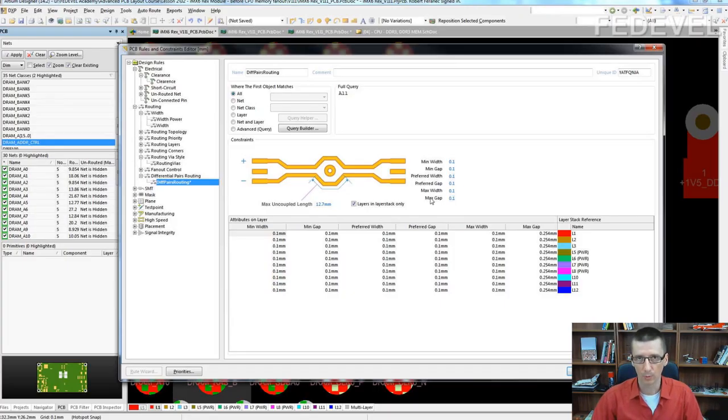Basically, we are going to occupy space with this default differential pair, which we will later just delete and redraw with a differential pair which will have the proper track width and proper gap for the specific impedance which needs to be used for that interface.